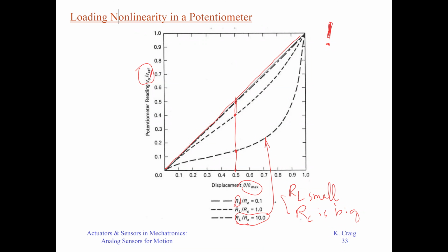But they are not proportional. You thought it is, okay? So this is unfortunate, and a lot of people ignore this. I want to remind you one more time that remember we did a quiz, and now we firmly believe, using a simple cascade of two voltage dividers using potentiometers, this is not 2.5, okay? It is actually 2.0. I hope this is a lifelong lesson you can remember.